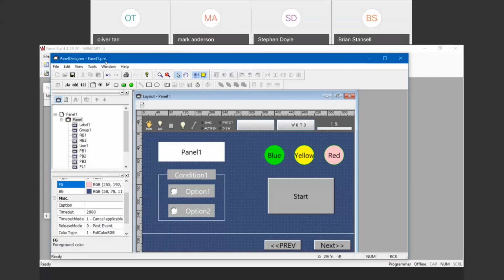Tony asked, does the name of the panel screen matter when loading on the Teach Pendant? Brian said that the only name that matters is the top level panel screen. It must be called main.pns, that is the file that the Teach Pendant button will be calling.